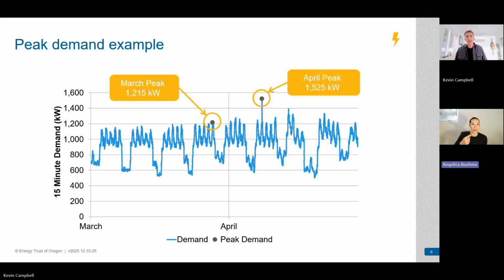They had an operator come in and flip the furnaces on in that same 15-minute increment. And they were able to stagger their start times for those furnaces, and this brought their demand charge down by a whole lot over the course of the year. They saved thousands.